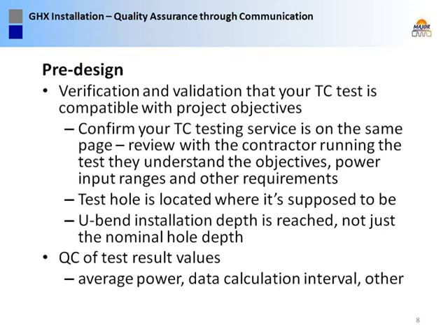So before you get your test done, you want to be visiting with whoever's going to be running that test and verify they understand the parameters, they understand the location, and the importance of why you sited it there. Another thing that we see that's kind of loose sometimes with some people that do testing: if we spec a 400-foot test, they'll get down to 360 or 370 feet because of drilling issues and not tell anyone. And I have a problem with that because we may be needing every linear foot of borehole we can get on a limited urban site, for example. So I make a very, very strong point with the drillers we use that if we say 405 foot, we mean 405 foot to get that U-bend into. And also we like to make sure that they're using the right power settings on their data log.